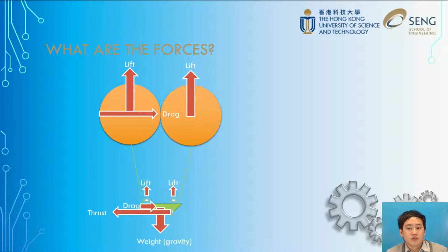In the situation of an airship, there are 2 types of forces that you have to pay additional attention to. As the buoyancy force almost balances out the weight of the airship and the projected area is large, the airflow or the air current will play a significant part in the whole journey. So make sure that you pay attention to the external wind force or air current acting on your system. Besides, you're also going to use propellers to generate the thrust for movement, and the torque reaction has to be taken into account in the design process.